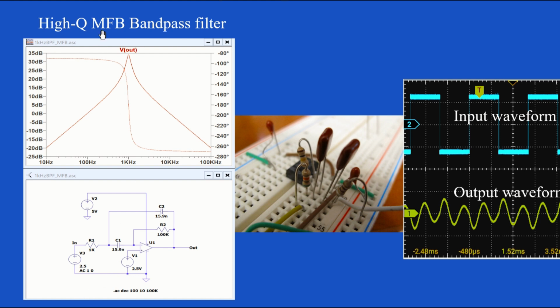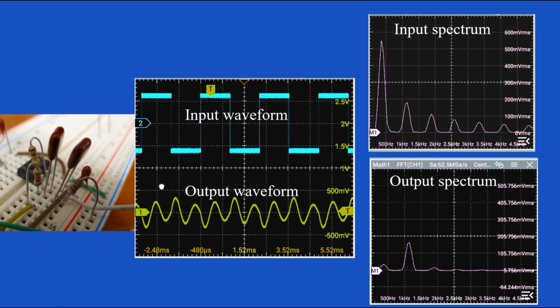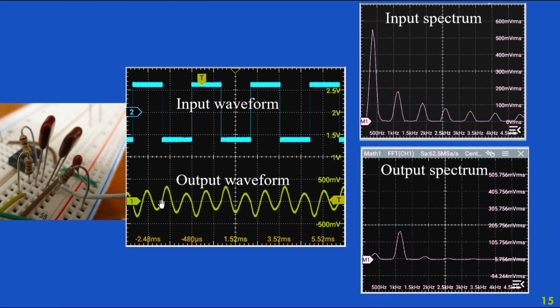This is a so-called multiple feedback op-amp filter. You can find ways to design this searching on the web. And I designed it, I think it was a Q of 10 or something. And so it's a very sharp peak at 1 kilohertz. The idea is to reject 330 hertz, which is down here, and likewise with the higher harmonics. And lo and behold, when I built it up and looked at the output, I got the third harmonic out.